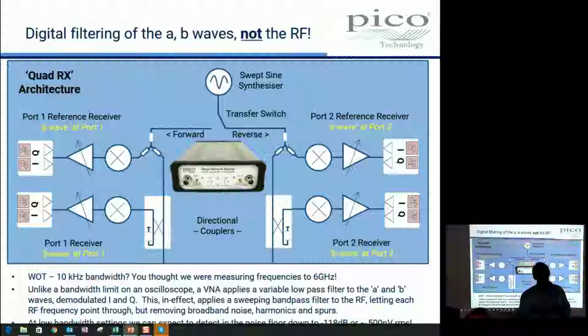Now the importance of that is if I select things down to, say, 10 hertz, then I can't see changes that are happening quicker than 10 hertz. So if I was drawing this gain plot as a line, isn't it? And if it had information on it going up and down that was faster than 10 hertz, I wouldn't see it, right? If I went too fast. But if I slow down and I draw it slowly, then I can filter that, can't I? And I won't remove it because the measurement is changing more slowly. And this is why when we put the 10 hertz filter on, the rate of change of the sweep, the source, had to slow down. It slows down to let the filter settle before we make a measurement of gain.